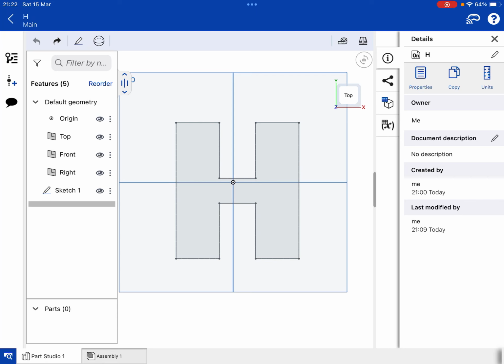Okay, so this video will continue our look at how to use Onshape. In this case, we're returning to the letter H we've made previously. If you recall, our first shot at making the letter H was really rough, really untidy. In our second go, we used some tools in Onshape like coincident, equal, horizontal, vertical to tidy everything up, and we ended up with this.